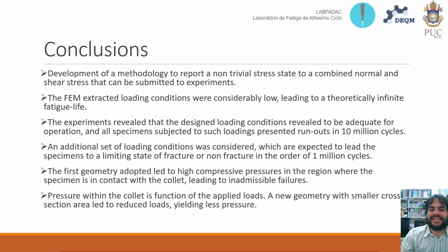All of this leads to the following conclusions. We have managed to develop a methodology that could report a non-trivial stress state to combined normal and shear stress amplitudes, that could be put to test. Finite element method extracted loading conditions were low, leading to infinite fatigue lives.